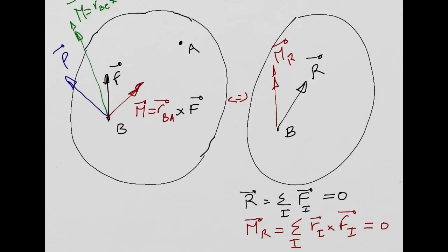Of course, we are going to do many examples where I ask you explicitly, construct the equivalent system force moment in point A or in point O. I will ask you to do that. But when you are solving an equilibrium problem, this point B that we have here in the slide can be any point of your structure. What it means is that you need to concentrate everything in that point: the resultant of the forces and the resultant of the moments.